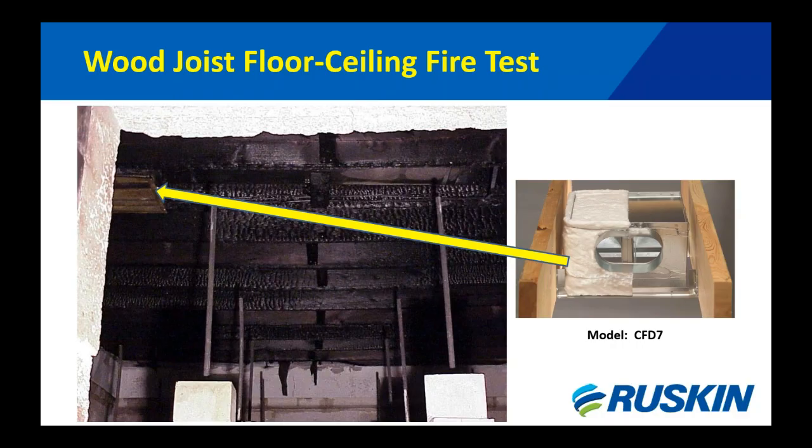On the physical product, the damper label, the UL listing label, won't actually reflect the 1-hour rating. It simply states ceiling damper. The way this works in the world of UL is ceiling radiation dampers are only qualified to the extent that the ceiling they're being applied in is qualified. So if I have a steel joist suspended floor ceiling system that's 2 or 3 hour rating, then the radiation damper being applied also takes on the same 2 or 3 hour rating. So whichever the case.